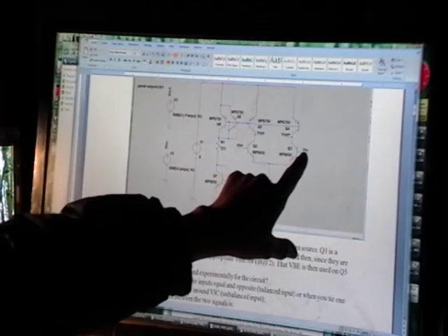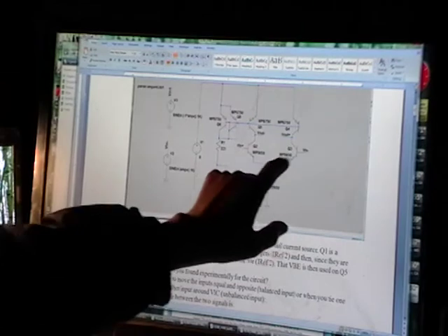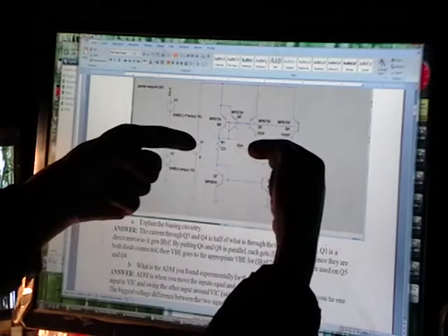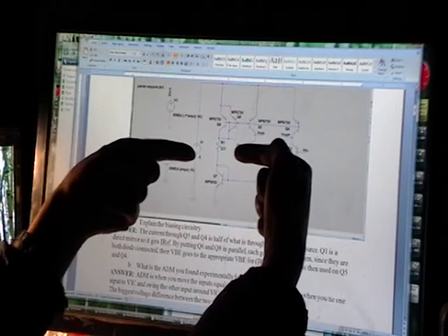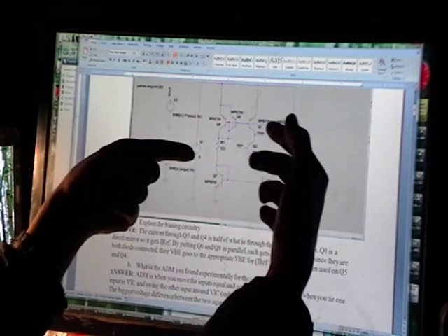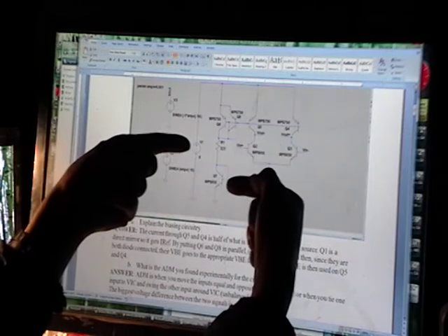Okay, and that 4 volts over here, that's the average voltage, that's your VIC, that's your common mode input. So you would put 4 on here and swing this a little bit and see your amplitude on your output. Now remember, in the common emitter, you compare the output to ground.